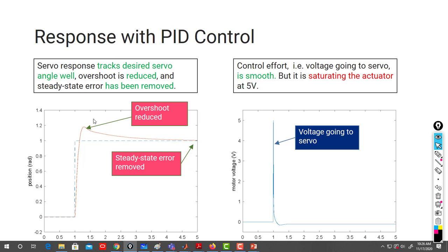Good. So it depends on you. If you don't want to consume your actuator, then maybe you need to not have a lot of constraints on your desired response. Don't say I want a perfect desired response, perfectly tuned, very fast with no overshoot and with steady state error equal to 0. No. Then you decide what you want to do. Maybe you decide to change the actuator at the end, but this is a more costly solution, and you need to change the system. Okay.